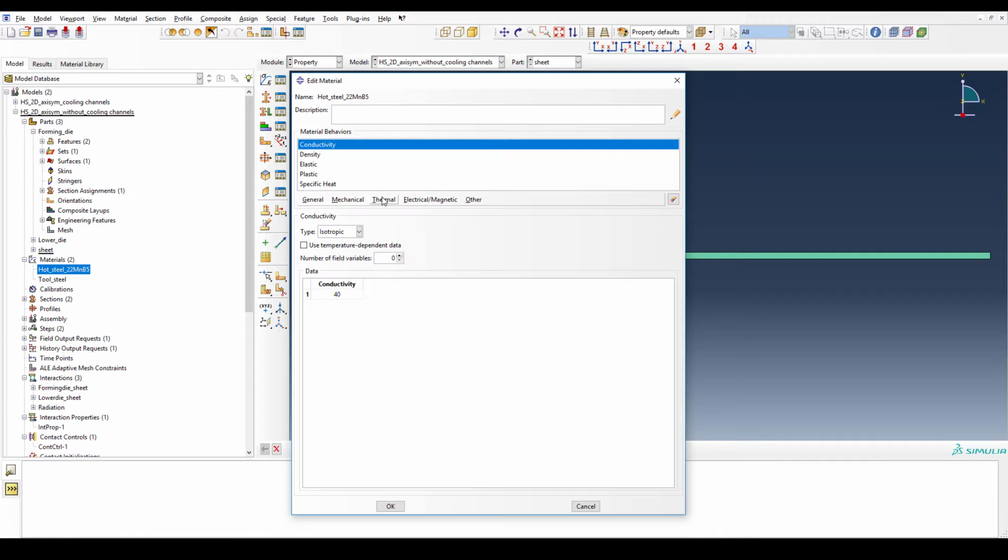Yeah, exactly. So I guess the correct explanation, and it's actually okay to not use it here, even though we have emphasized it's important in forming operations. Just think about it. In general, the volume times the strains gives you an idea or a feeling for how much heat is generated. And your volume in this sheet is very small compared to its contacting surface.